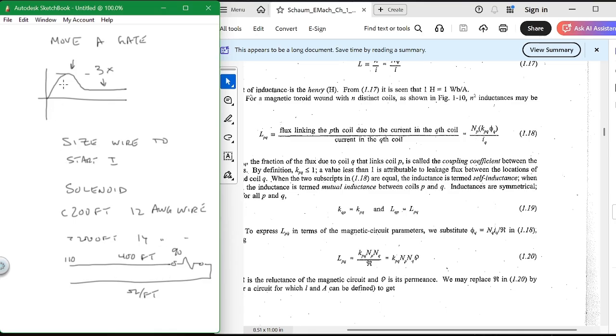And that current times the ohms per foot gives you the amount that you can actually drop. So in other words, we really didn't care. You just had to know that if you were under 200 feet, you could use 14 gauge wire. But the reason that you could use the 14 gauge wire was because the ohms per foot was sufficient that if this turned on at 90 volts, after it turned on, you didn't care because it was down here.